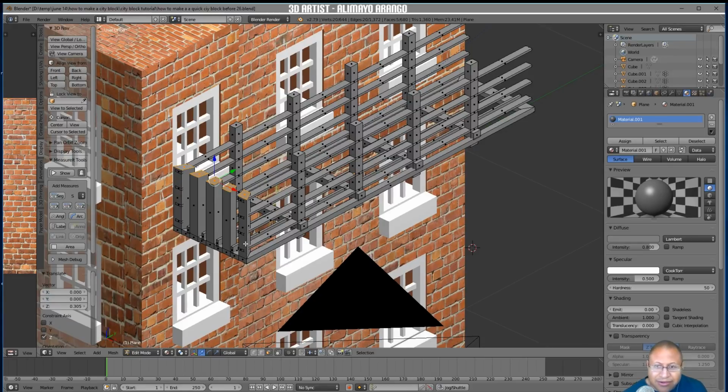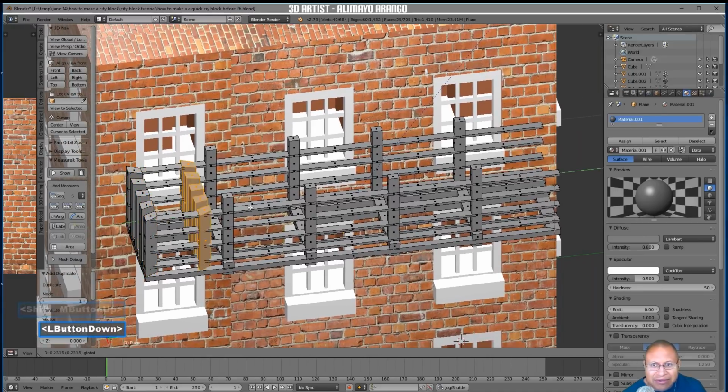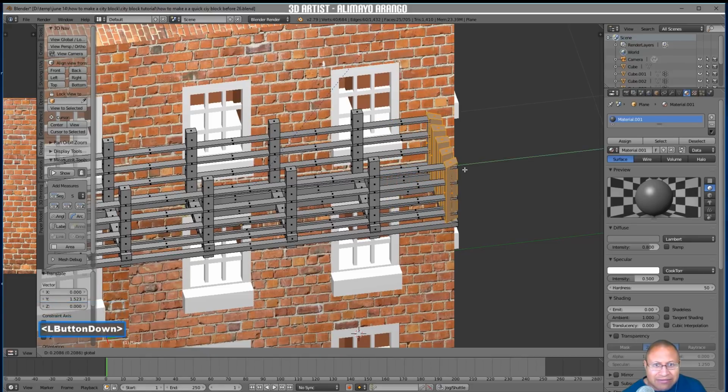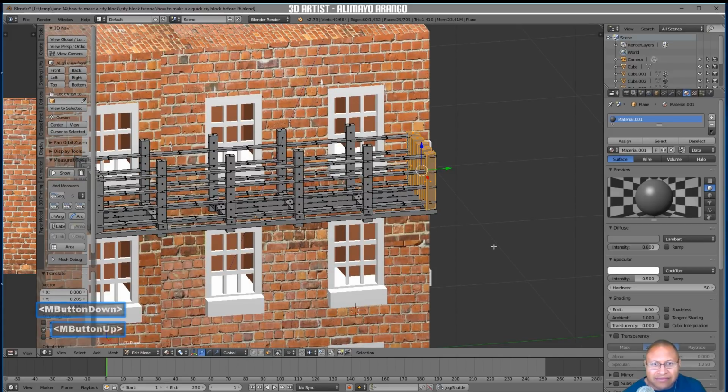What I'm going to do is hold Shift and then Alt to select around here. So I have the top part selected, right? Because I'm holding Alt, when I clicked on the side here, I selected all the way around here, all the way around here, all the way around here. And I already had the top selected. So now I'm going to hold Shift, press D, and then right click. I'm going to move these pieces over here like that. Now I'm going to press A to deselect.